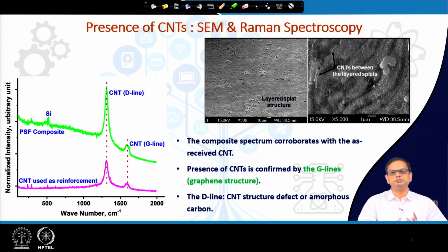So, the powder mixture was ball milled for a long time to achieve good mixing, because nanoparticles and nanofibers tend to agglomerate. Okay. So, here the basic technique applied was mechanical mixing, to achieve homogeneous distribution of the fiber particles in the matrix. It goes through high temperature and high energy ball milling, and that is why some amount of defects gets incorporated once the composite is made.